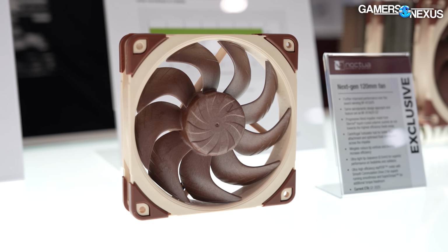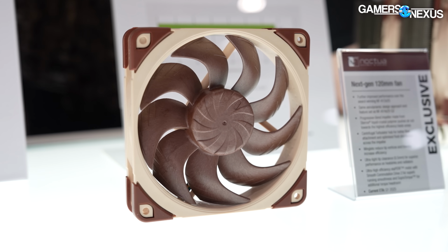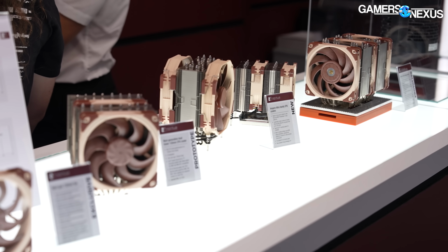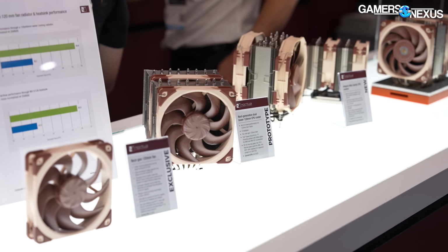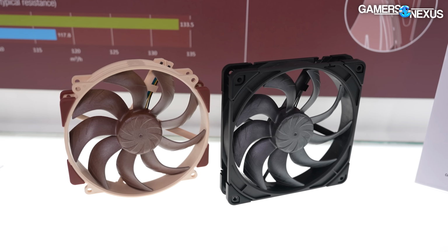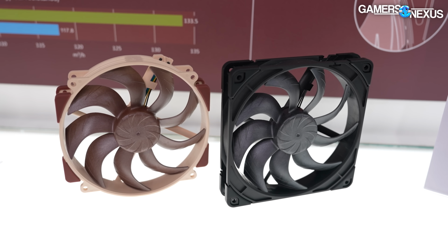How do you start to even decide on this stuff? I mean, is it all CFD simulation? Is it just such a known science that you kind of know? Oh, well, there's certain things like blade count, blade surface area, to a certain extent blade curvature, definitely blade profiles, where very good numerical prediction models exist.